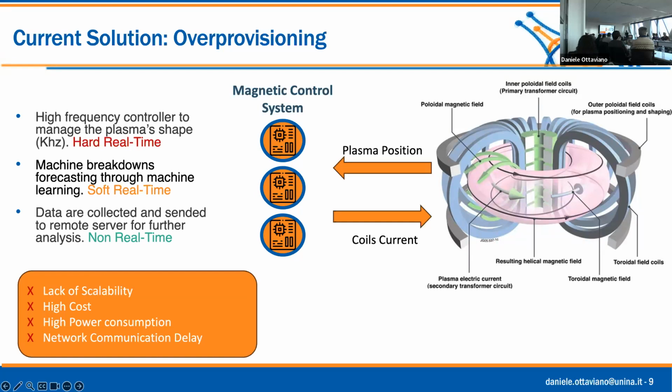And what's interesting is that they're so concerned about temporal interference, the temporal behavior being corrupted, that they throw away any layer of OS, even a simple OS. They go full bare metal. They turn off caches. They try to make it as predictable as possible. They strip everything out because they don't trust anyone. Yeah, so they are going to execute bare metal code on, for example, one single core using one accelerator on a board that maybe has several cores, several accelerators, stuff like this.